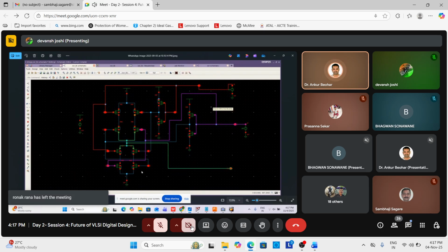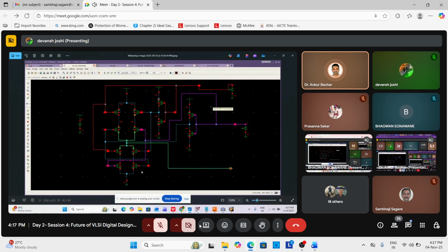Their purpose is that with the help of these EDA tools, the fabrication is also done cost-effectively by our government of India, SCL Mohali. Initially they can implement it under 180 nanometer for just a prototype, but later on it will go for final implementation, that is manufacturing and all. So the chip is sent for tape out that contains all geometrical shapes. Once you design this graphical data system GDS, then we will have the final GDS2 file, and you can go for the implementation on the circuit like this for tape out.